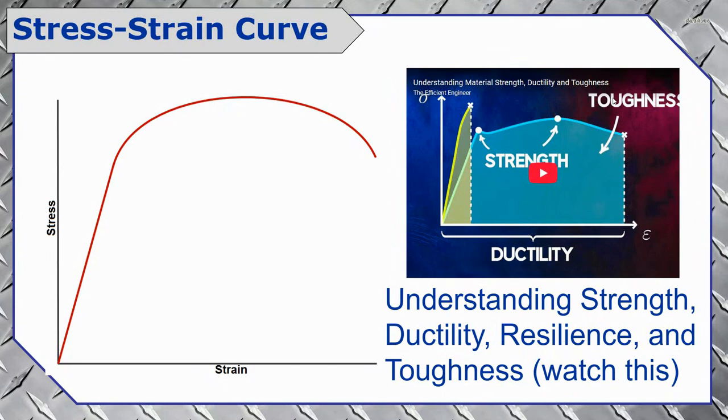If we can calculate the stress and the strain in a sample that we've tested, we can plot those two measurements just like this, with stress on the y-axis and strain on the x-axis. It looks a lot like our earlier curve that was showing us force and elongation. But a force and elongation graph does not take into account differences in sample size.